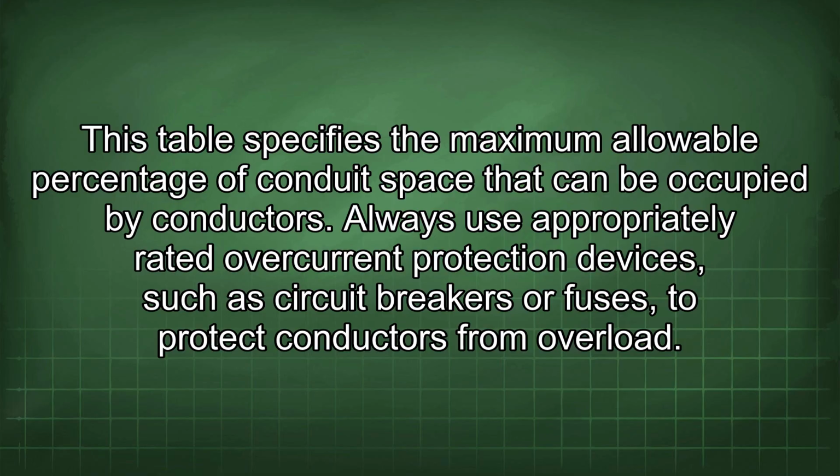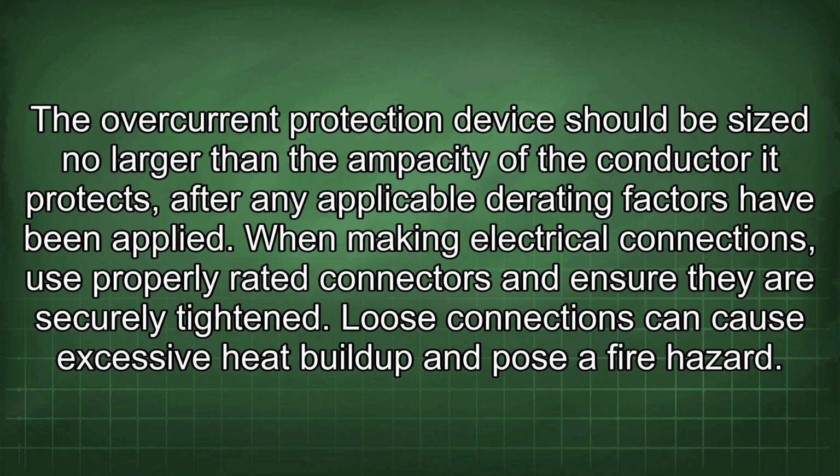Always use appropriately rated overcurrent protection devices, such as circuit breakers or fuses, to protect conductors from overload. The overcurrent protection device should be sized no larger than the ampacity of the conductor it protects after any applicable derating factors have been applied.